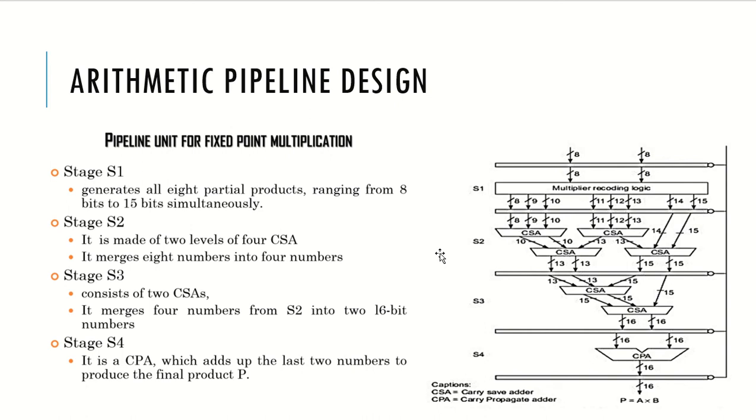Okay, so the carry save adder will work. As you know, if you don't have n bits, you will have to make them n bits by adding zeros to it. So making all that done, these 8 partial products, which were ranging from, the first one was 8 bits and the last one was 15 bits in length, putting them together, you will merge them together as 4 different numbers. So out of the 8, now you have 4. Okay, so 4 different numbers.